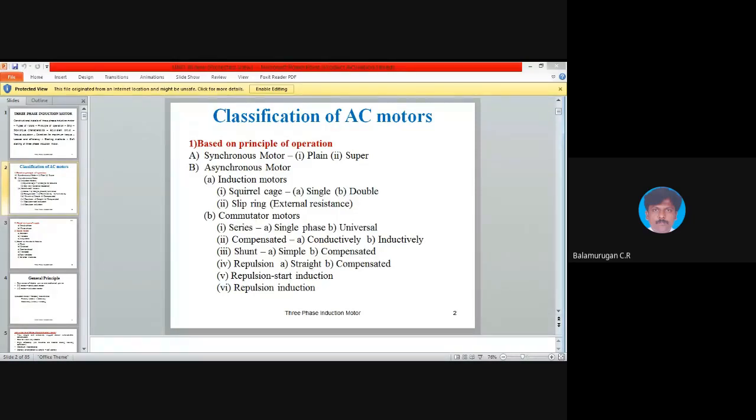How will the rotor construction be in the case of an induction machine? We'll have a stator winding like this. So this will be the stator winding, and the rotor winding will be almost like this. This is RYBN, this is the stator circuit, this is the rotor circuit, and here we'll have an air gap. This arrangement is the actual construction of the induction machine. In the stator we'll have three windings with the neutral point, and the rotor circuit will be short circuited. We will have either a winding or copper bars.